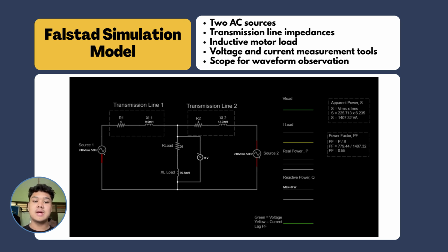Besides, we also added measurement tools so that we could measure important parameters such as the load voltage and also the load current. We also used the scope function in Falstad to observe the waveform behavior of the system in real time. So the purpose of using Falstad is to make sure that our theoretical calculations and analytical results are correct. Instead of only solving equations manually, the simulation allows us to visualize how the system actually